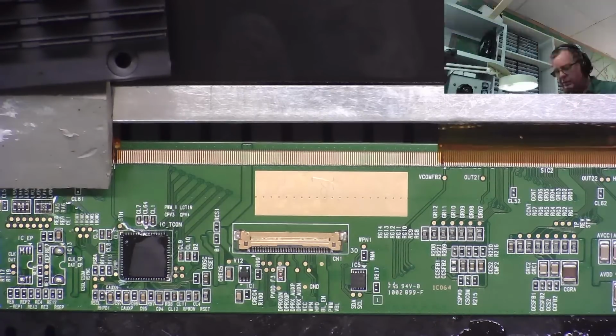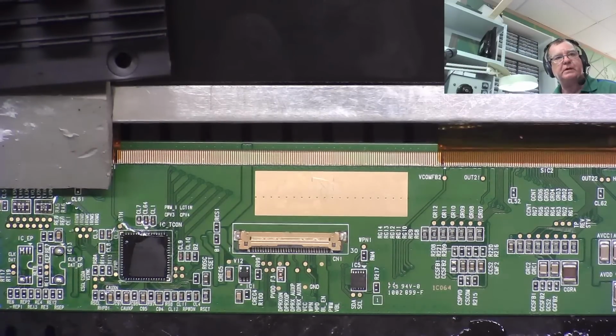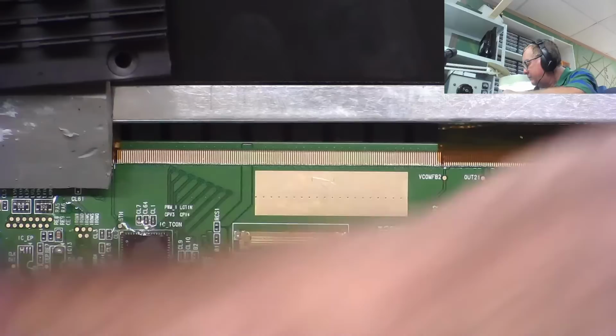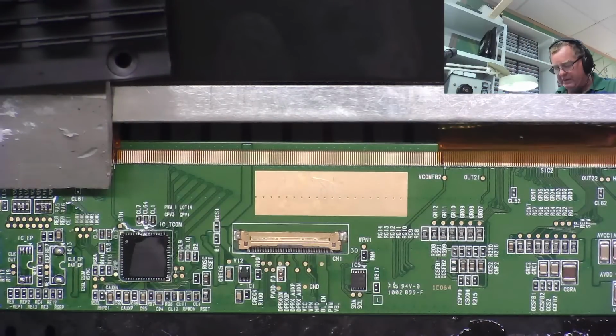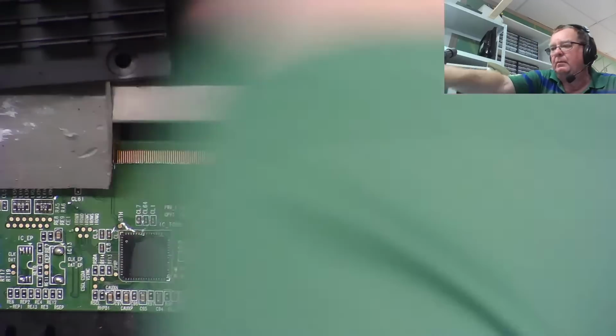Okay, so this other one, I've just removed those two chips because they came off really easy compared with the other. Well, the other one was easy enough. These came off very easily compared to that big square chip that was a right pain. Let's find a bit of solder braid, and I'll clean these blobs of solder off here, where I basically bridged all the pins together, as you've seen me do several times now. We'll clean this up and down.